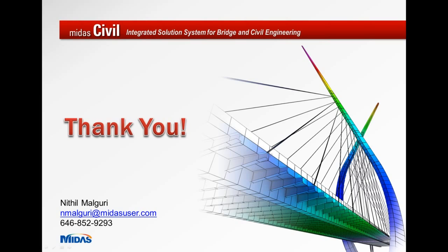There is another question by Ben. The question is, how did you model the steel beam elements and cross frames? In Midas Civil, you can model the steel beam elements. I used the composite section for that, and to connect the cross frames with the steel girders, I used rigid links so that they can transfer the forces.